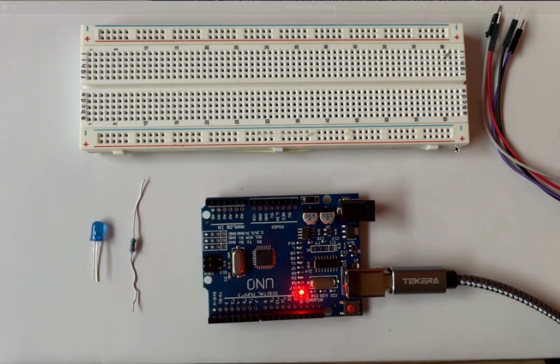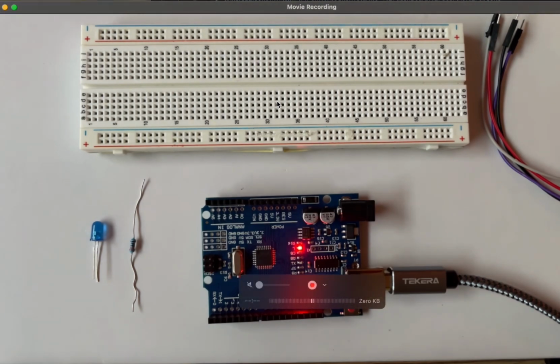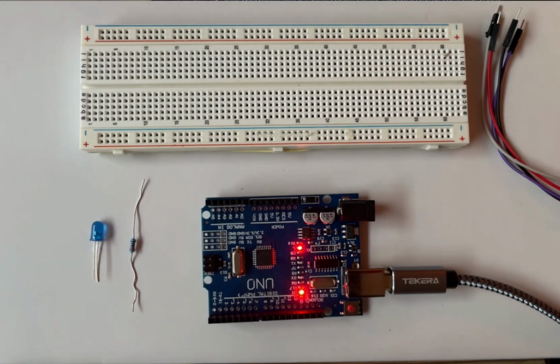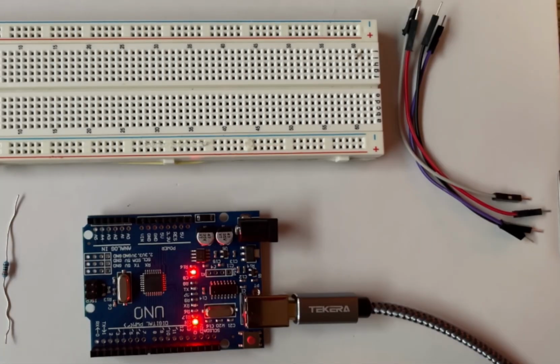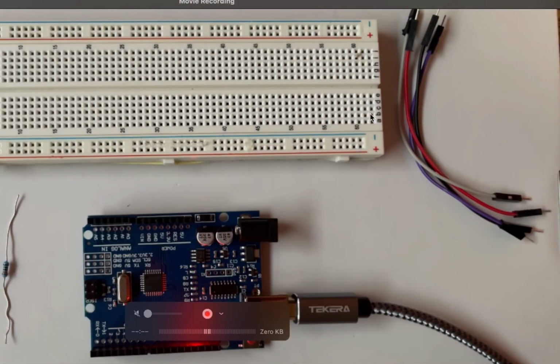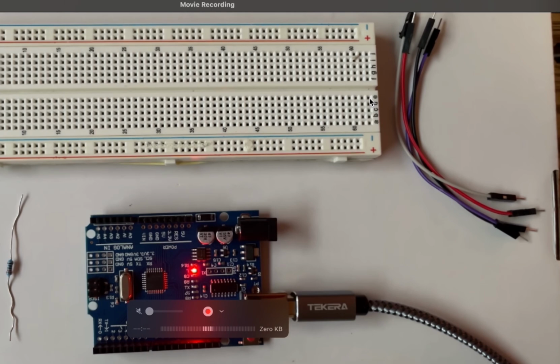We also have this thing which is called a breadboard. It's called a breadboard because it kind of looks like a bread, but it is a very trusty tool used in experimental circuitry. Now what you see over here, these columns are connected. So if you connect a wire over here, it's the same as connecting the wire on any of them. So it makes it very easy to make connections. They are connected vertically over here. These ones are vertically connected and these are connected horizontally.